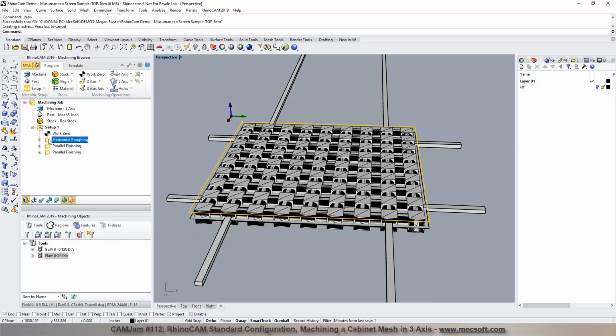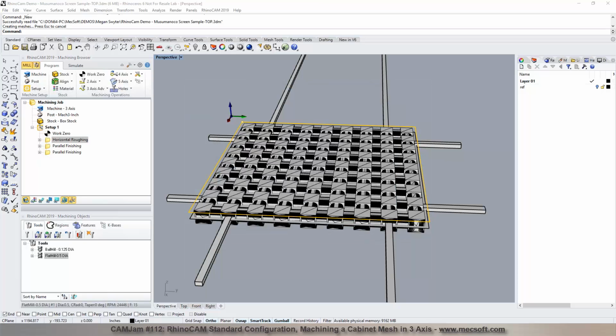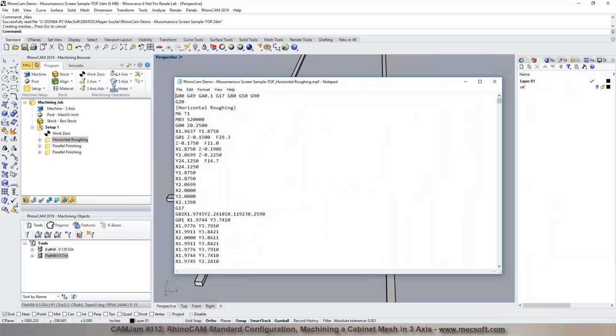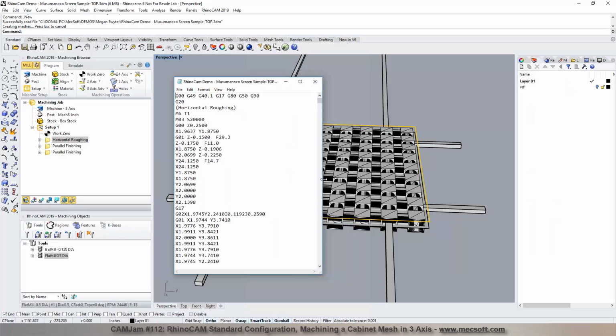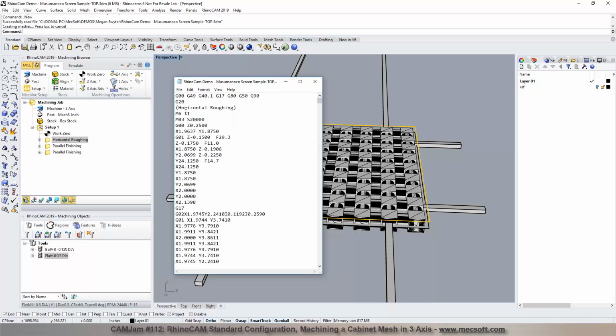It should. There we go. Let me bring it over here. Cool. So there's your G code for the roughing operation. And you see here tool number 1. So if you have an automatic tool changer, it's going to go grab tool number 1 and run that operation.